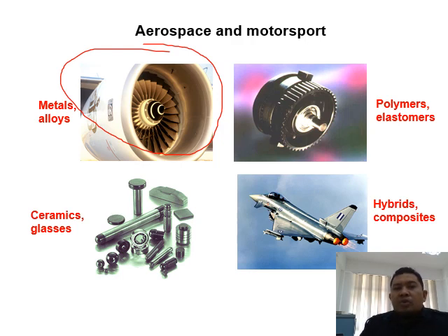Okay, and then the nozzle part also, when you compress the air and then push out the air, you have very high temperature, high pressure, high velocity, and so on. So over here probably you need to use nickel aluminum alloy mixed with ceramic particles and so on. Actually in metal alloys, not just metal alloy, probably over here you have composite alloy and so on.